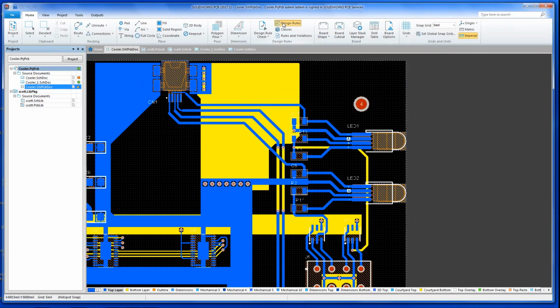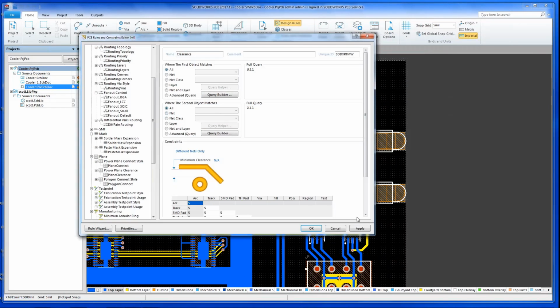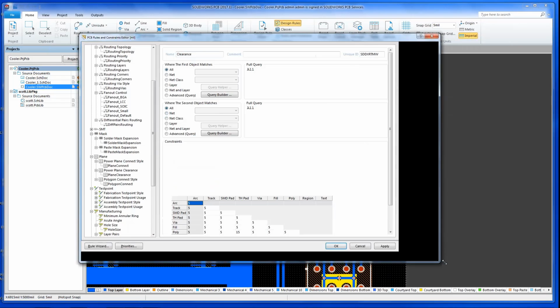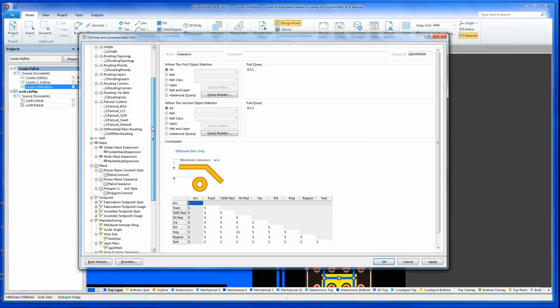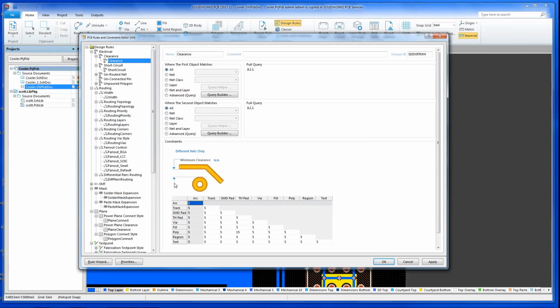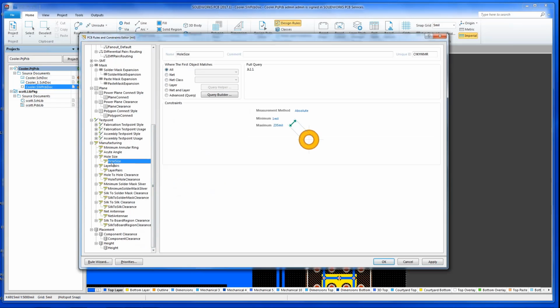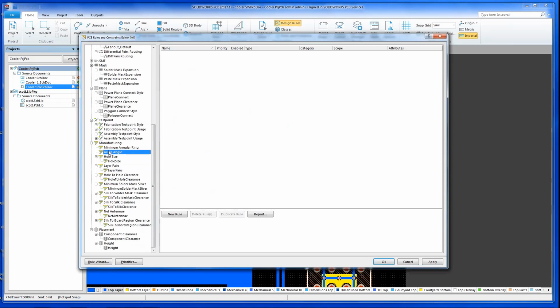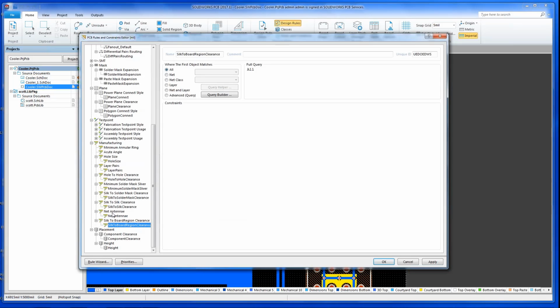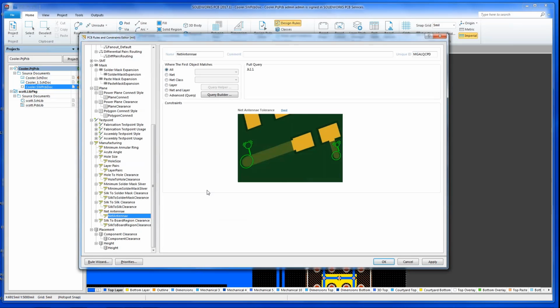Tool contains the design rules that we looked at in the presentation. This is the real time. So I've set these up for pretty standard manufacturing, including silk screens, solder masks, hole size information, minimum, maximum, acute angle, so that you don't get acid traps in your board, placements, silk to board edge, many net antennas.